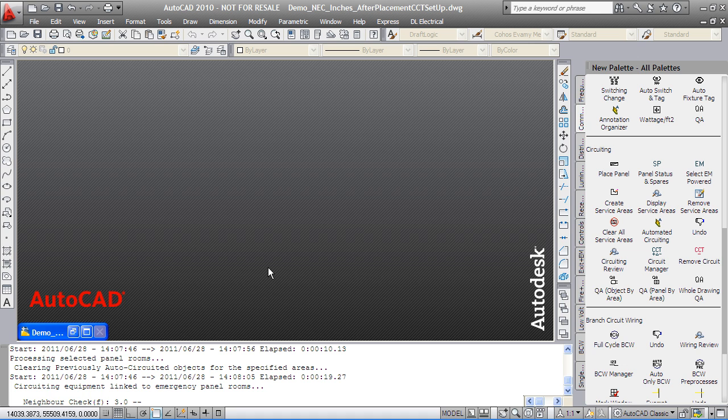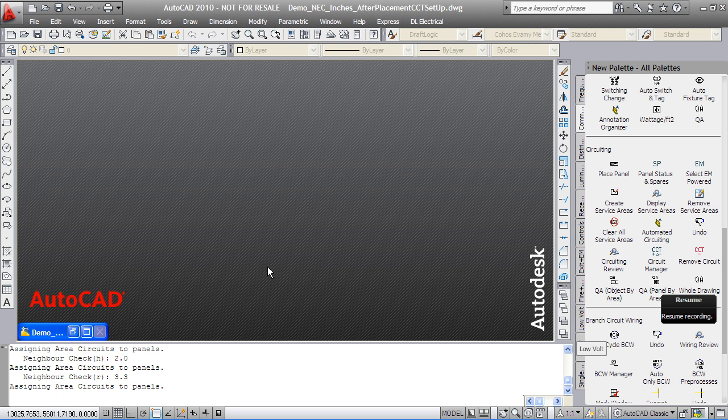Groups of circuits are used in 2s for single-phase panels and 3s for three-phase panels in order to maximize the opportunity for neutral sharing, when allowed, and thus reduce construction time and materials costs. Small motors will be serviced by the same panels and same circuits as receptacles of compatible voltage if you decide to allow DraftLogic Electrical to do that.